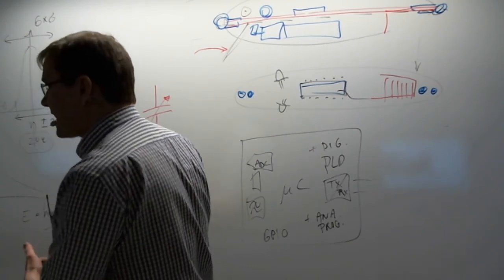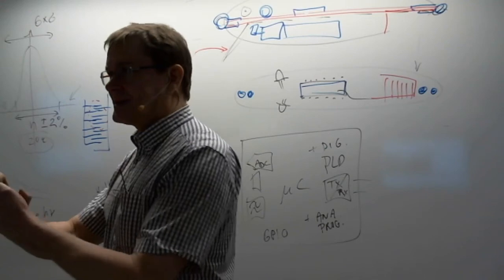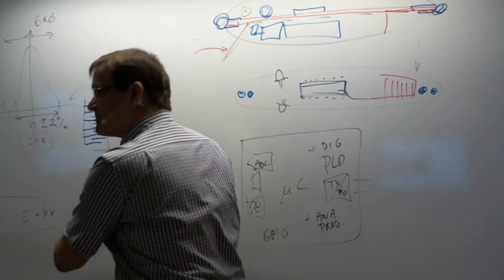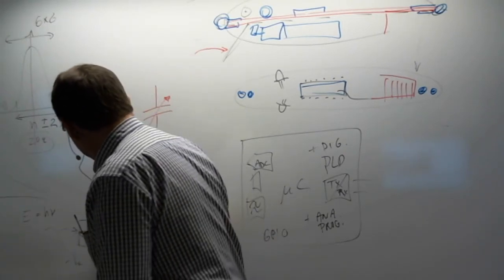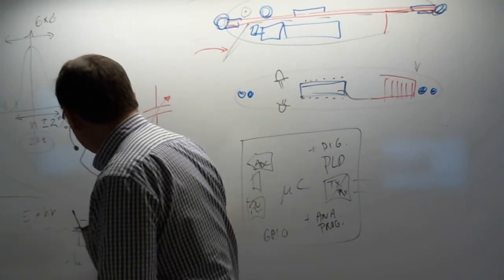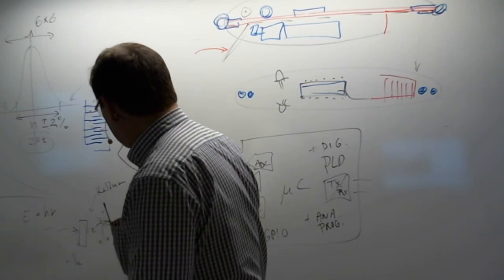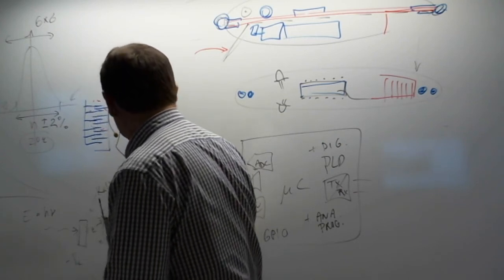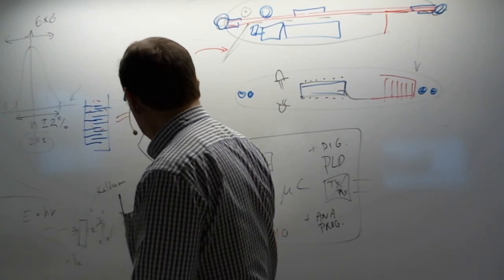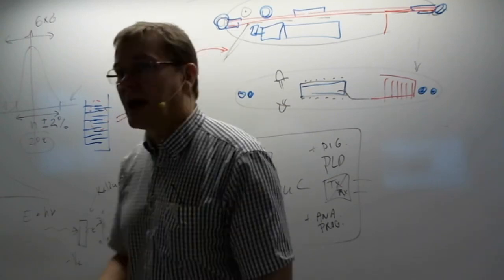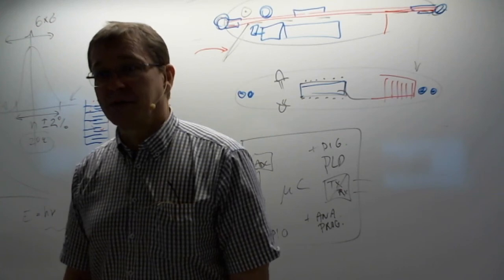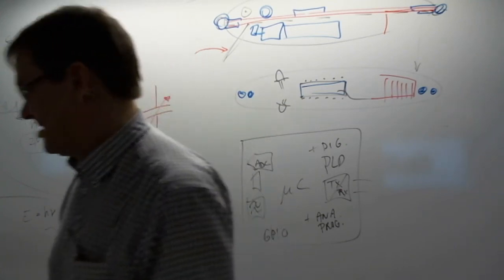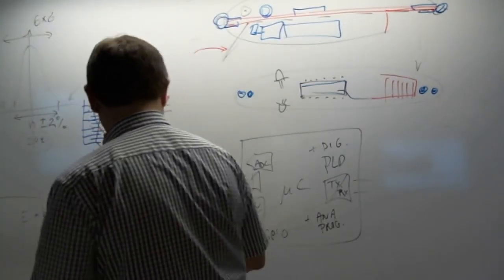The electron starts traveling there, hits the dynode, and it multiplies. Because you are actually accelerating the electron, it hits and releases the energy into this material, and then basically you get 2 or more electrons, and then you can have a chain here, an acceleration chain, and finally you have even a microampere pulse of current coming out. Microamp. Okay.